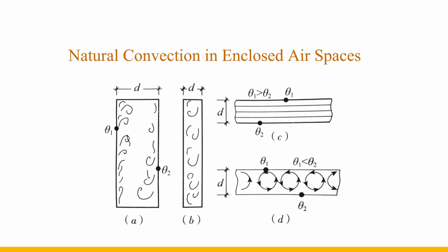This is equivalent to the heat transfer process between two surfaces of a finite air layer, including convection heat transfer and radiation heat transfer. Therefore, the thermal resistance of the air layer mainly depends on the thickness of the air boundary layer on the two surfaces of the interlayer and the radiation heat transfer intensity between the interfaces. There is no proportional relationship between the thermal resistance and the thickness. The convective heat transfer intensity is related to the thickness, position, shape, and tightness of the interlayer.